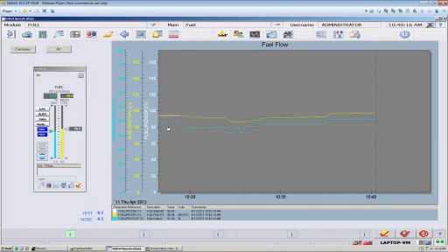Remember, our tuning parameters are all in terms of percent of scale. So this PV scale, our flow scale, is not 0 to 100% the way air was. This is in actual engineering units, 0 to 175,000 standard cubic feet per hour. So my change there